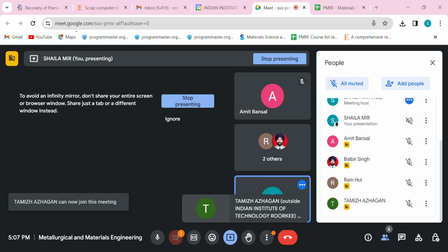Ma'am, the question was raised by me because there is a similar question in assignment 8 in which the specimen is made of glass. So obviously we can't use magnetic particle test, but for liquid penetration test on glass, I think you also have to see how it behaves. The glass is a transparent material, right? Will X-rays pass through the material, or will they be reflected? You have to consider that also, because for X-rays, it should pass through the material, and then your crack will be detected.